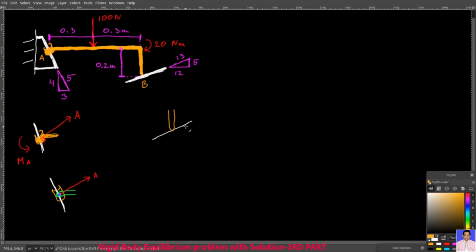There is no restriction to rotation about point B, and assuming negligible friction between the ground and the member can also translate along the ground. Only motion perpendicular to the ground is restricted. Thus, you only have one reaction force, which is normal to the ground. This is the force that the ground applies to the member.